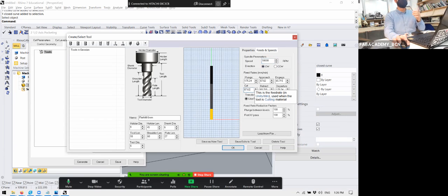And we have the cut speed. You see, I'm not touching these ones. I just touch cut speed. Cut speed is the horizontal cutting speed. I know this tool. I use it every day since like 4 years ago here. I know that the cut speed for that plywood that is class C is 5,000 millimeters per minute. And we start with this one, that is the cutting speed. This is the speed we want to cut.